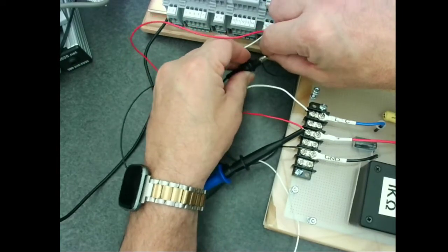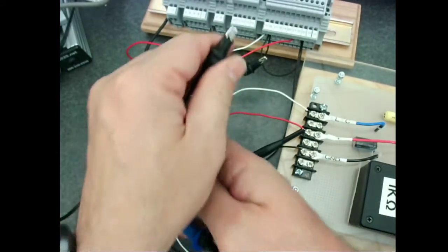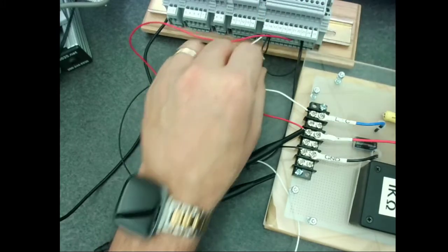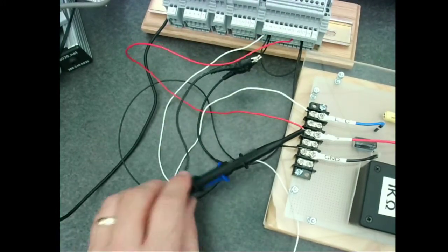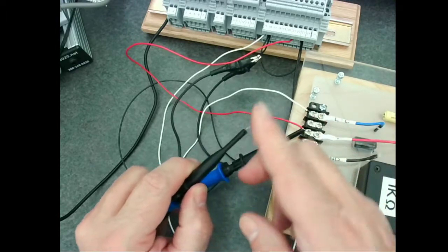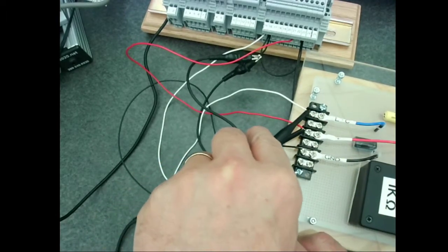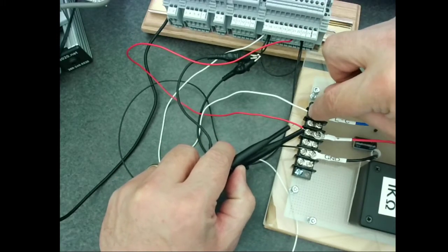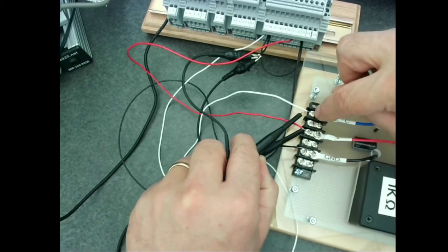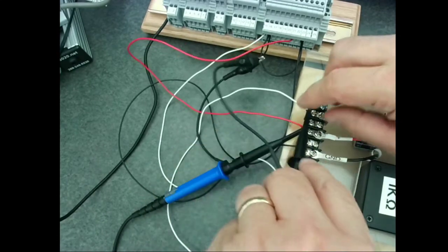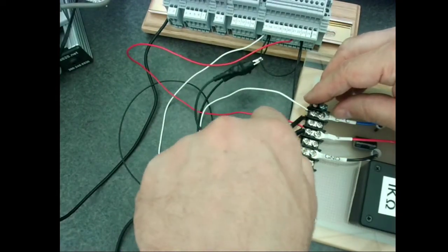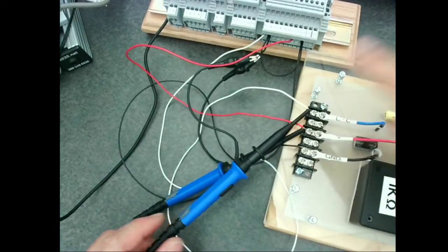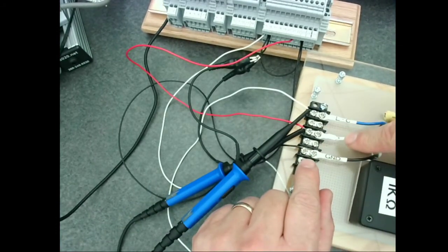And then I have my oscilloscope. I'm going to attach the alligator clip groundings for my scope so that my scope inputs are both grounded. Okay, and then I'm going to use the clip piece here, and I'm going to just clip right on that wire. I actually left just a little bit of copper bare sticking out from the screw here, so that I got enough that I can just get this clip on here. And so I have my input to the RLC circuit.